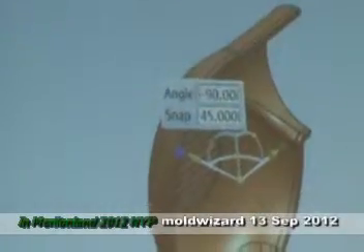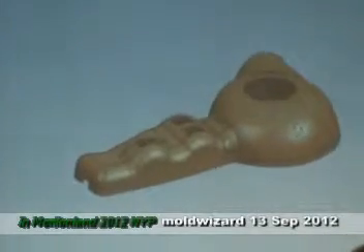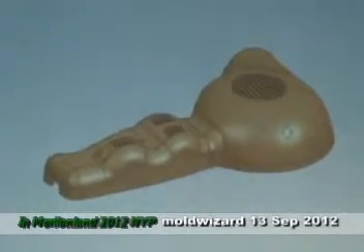You drag this small sphere and rotate by 90 degrees. That means if this is my product orientation inside the mold, I have no problem for ejection. That should be the correct orientation for the product.